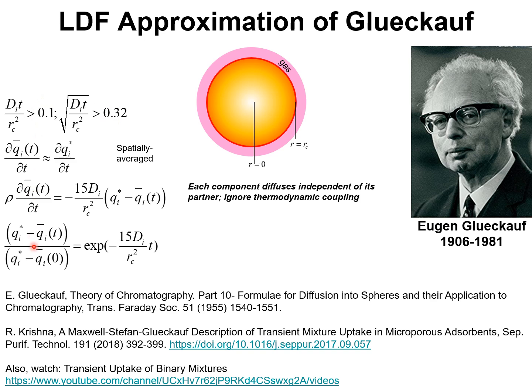If we make this assumption, then as did Glueckauf, we can relate the time derivative of the averaged component loadings at any position z as given by this simplified expression that obviates the need to solve the partial differential equations describing the transient uptake within the particle.